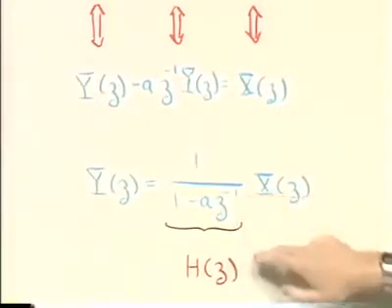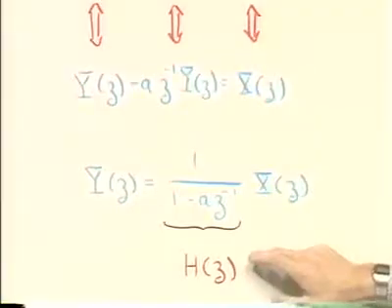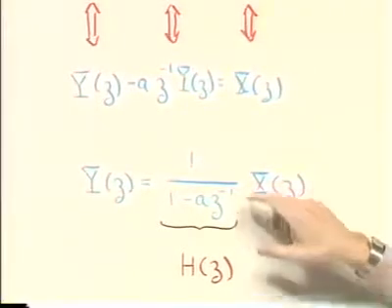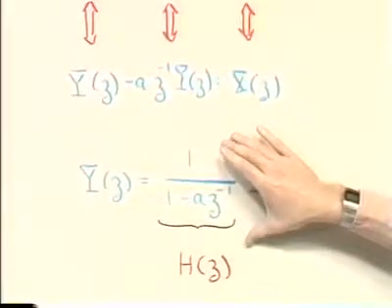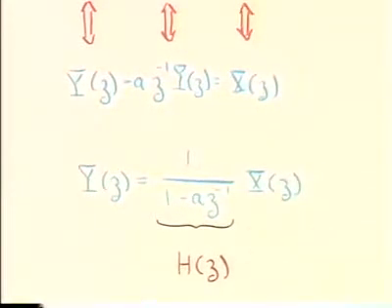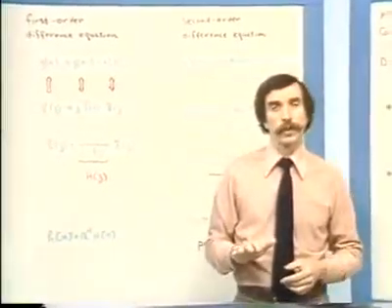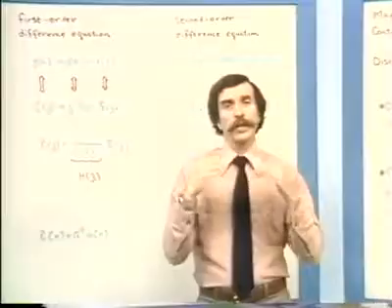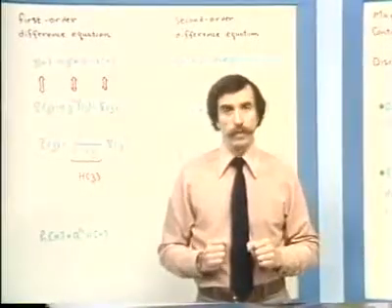And in fact, if we have this z-transform, we could figure out what the impulse response of the system is by determining the inverse z-transform. Except that that expression is an algebraic expression and doesn't yet totally specify the z-transform, because we don't yet know what the region of convergence is.